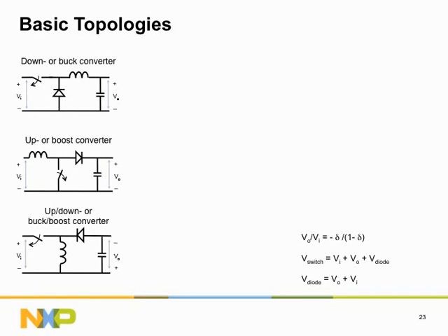The voltage rating of the semiconductor switches is given in the two subsequent equations. As you can see, the voltage rating of both the switches should at least be equal to the maximum voltage difference that exists in the circuit plus a bit of margin.